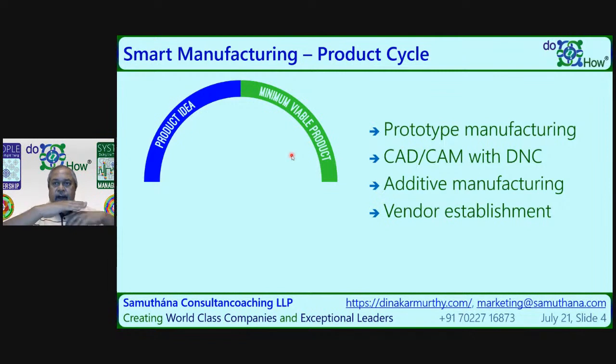Whereas in the case of additive manufacturing, you are basically welding two items together, two molecules together. Therefore, there is no concept of the structure and the flow of the structure. There is no structure. The microstructure would not show you that it is overlapping like this, which is what happens when you are doing rolling or cold rolling or hot rolling or extrusion, forging, these processes.